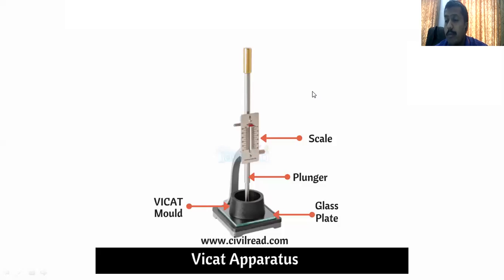How you are going to compact: just take one corner of that glass plate in your hand and try to compact it. You have to rotate that corner, means 0 degree, 90 degree, 180, 360. Likewise, you can do the compaction. Anyway, I will show it at the time of the experiment on Saturday, how we are going to perform it.